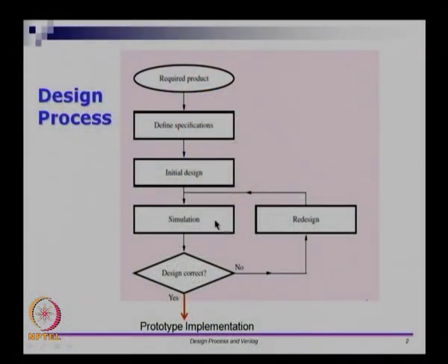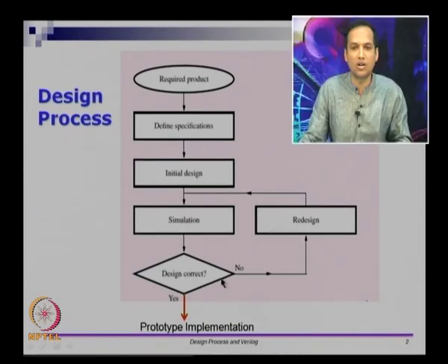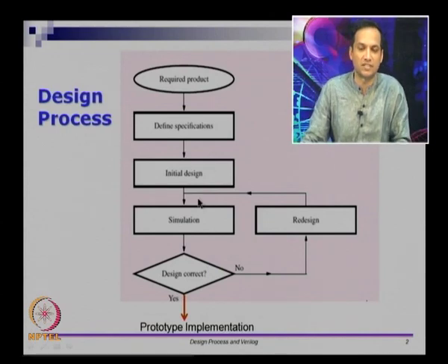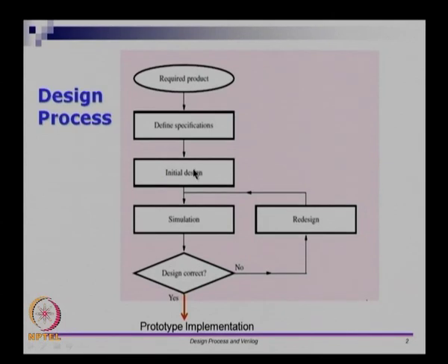So this is called front end design, and this process of doing simulation, taking an initial design, writing the design in Verilog, do simulation, finding out whether it's correct or not, and redesign and loop through it if the design is not correct. So this process is called front end design and verification. So you do a front end design using Verilog or VHDL. VHDL is another popular language, and this process is called verification, and verification takes quite a bit of time. So about 60 to 70% of product's time is spent in design and verification. So it's a very important task.